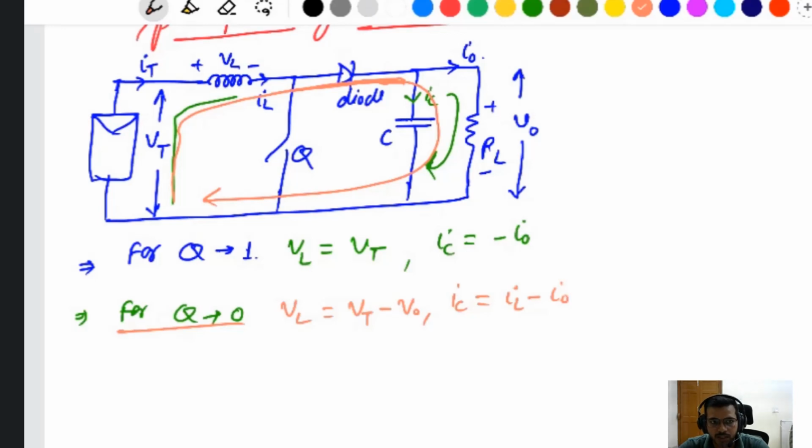If you charge the inductor, flux is stored, and after that when you discharge, the flux decreases, and the increase and decrease of flux will be the same. It means volt-second balance is the flux balance also. If you charge more, the flux increases, and the charging flux is more than the discharging flux. At that point, the inductor gets saturated.